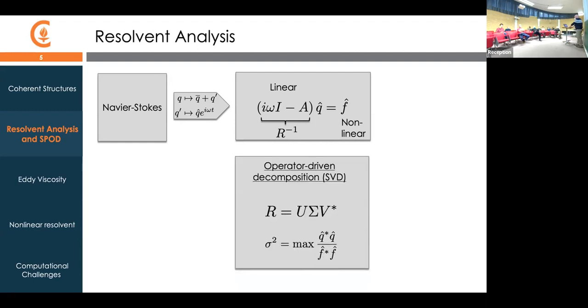The idea in resolvent analysis is that if I invert the linear portion of the operator and put it on the right-hand side, then it tells me that the output Q is related through this linear operator to this nonlinear forcing F. Because that linear part of the operator has quite a propensity to amplify certain patterns in the forcing into patterns in the output, the notion is that if we do an SVD of that operator and look at the high gain relationships between specific forcings and specific outputs, that will be a good way to head towards model reduction.